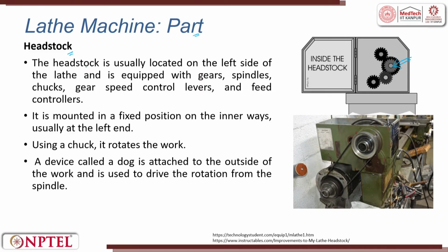Right. The headstock is usually located on the left side of the lathe and is equipped with gears. It can also have splines, chucks, gear speed control levers and feed controls. So, it is mounted in a fixed position on the inner ways, usually at the left hand side. Using a chuck, it rotates the work. So, that is where this gear train is attached to the spindle.